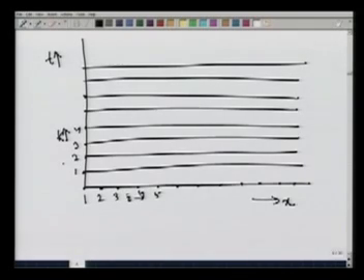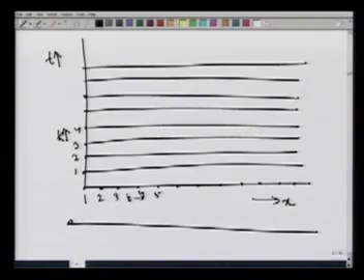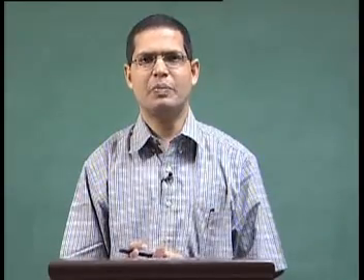So if I am interested to know the variables throughout the channel, don't forget this. This is the channel, these are the different nodes which I represent in this grid as i's, and on these nodes both h and u. If you remember the governing equations as we wrote for the continuity equation and the momentum equation, the independent variables are x and t, the space and the time nodes. Okay.